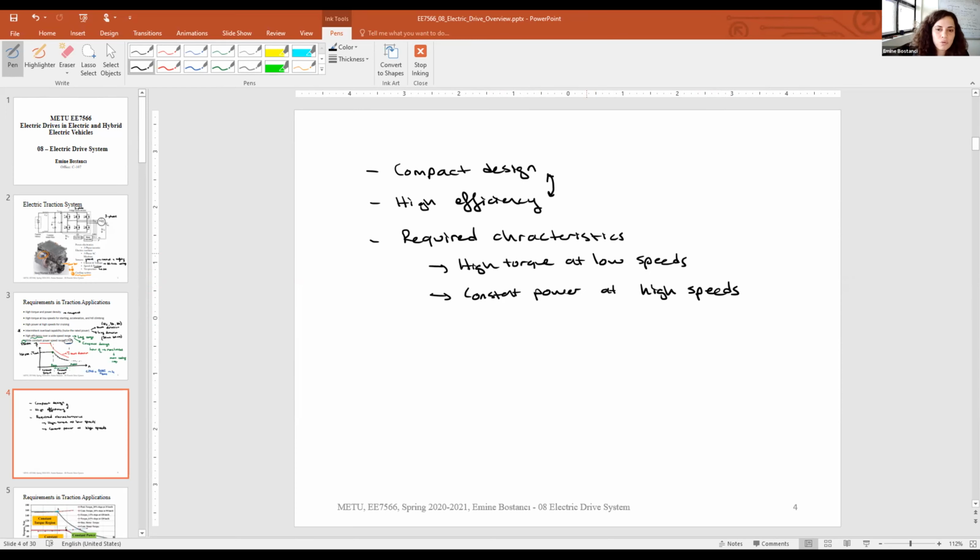So I found some torque speed characteristics. It is very common for us to just show the torque speed characteristics in the first quadrant. You can just assume that we are going to have similar torque speed characteristics in the other quadrant, because you know that our electric motor, even if you are driving in only one direction, is going to operate in two quadrants.